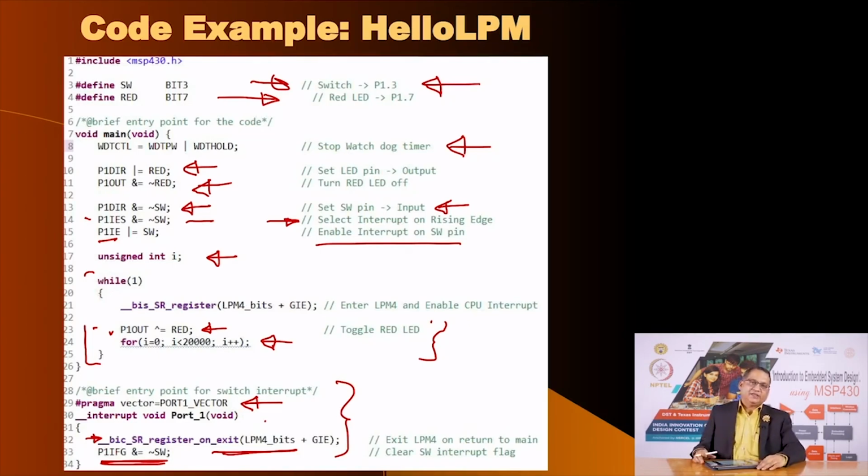This is an interesting exercise to see how you can play with the low power mode, and how you can have external peripherals exit the low power mode. I strongly recommend that you experiment with this code, especially by playing with this instruction, by commenting it out or keeping it in your code to see the impact. So, we are done with the description of the low power modes as well as how to connect a simple 7 segment display to the pins of an MSP430 microcontroller.